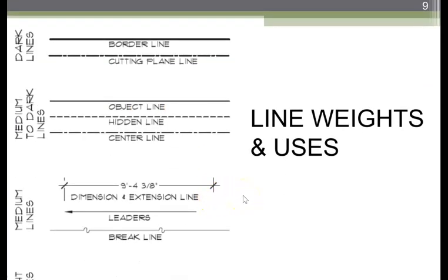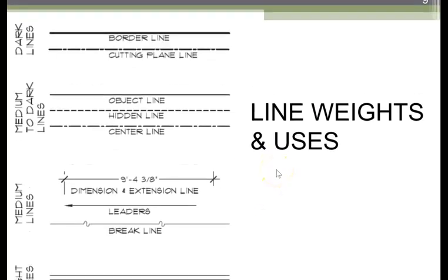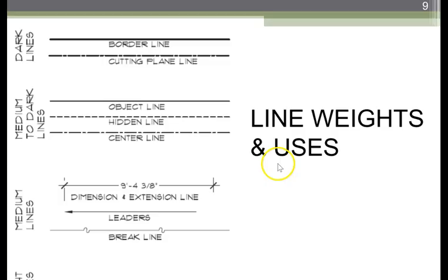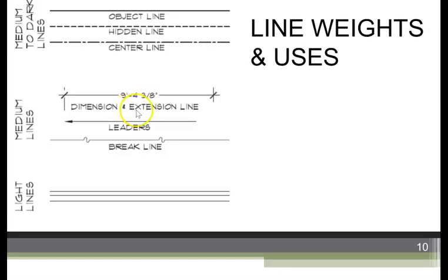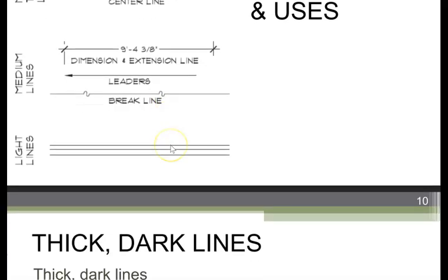Okay, here's the topic that you need to remember for your own drawing, is that basically we have three line types. We have the dark line, shown by these two examples. We have medium to dark lines, which is the object, the most common thing that we see, and usually this is a border, frame, or a floor plane. And then medium lines are used to show dimensions, could be a dimension line, very sharp. And then light lines are reserved for hatches and less important materials, maybe the outline of an oven or something like that.